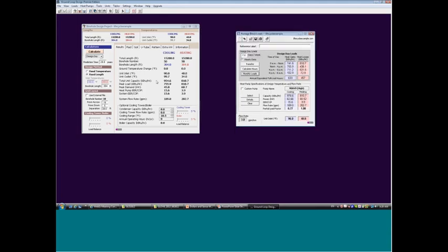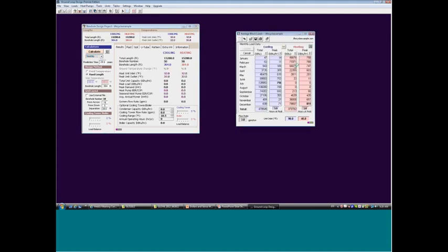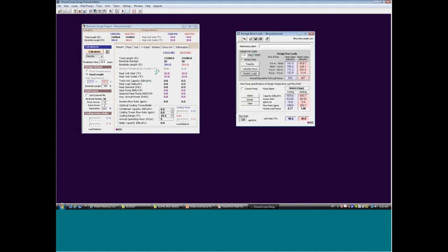What I've chosen, well, I've already optimized it basically, but I have 50 boreholes, a 10 by 5 grid with 20-foot spacing. And I'm just going to run a monthly simulation. In this example, I'm just going to take these monthly loads and plug and chug them through this design. The output results are going to be my predicted temperatures in my loop field and then my performance in my mechanical equipment.